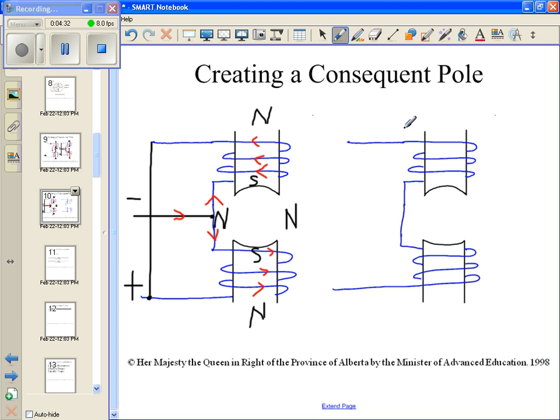The one on the right is the one where we have one coil that's wound clockwise and the opposite down here. So this one we actually are going to make a series connection. The series connection is already pretty well made right here. In other words, this is one winding, so it really already is in series. We're going to apply negative there, again freeze framing that AC sine wave for a fraction of a second, and we're going to assign a polarity of positive there.